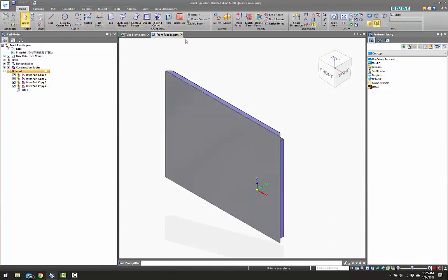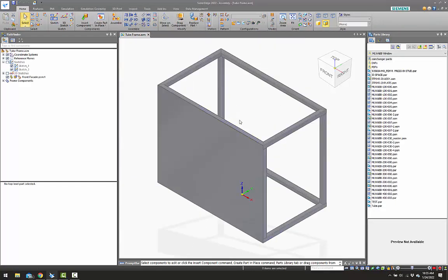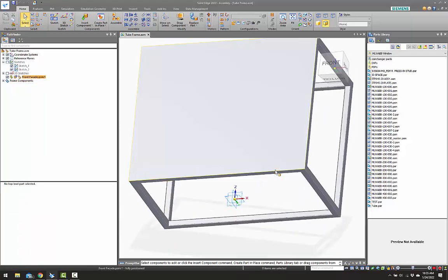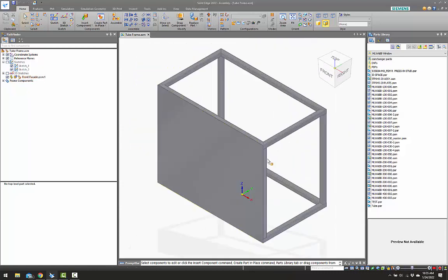So again, we need to be able to have good design intent approach, knowing that that's how this part is made, so that I know that if I change the length of this, that it will update. But if I change geometry totally, that I may end up with some broken links. So just keep that in mind.